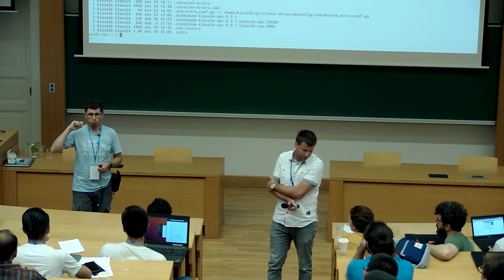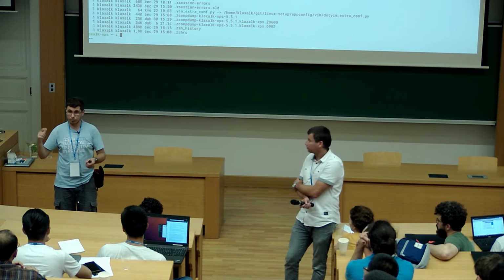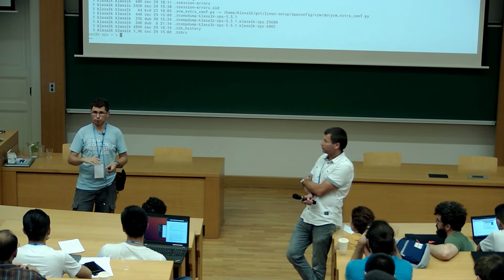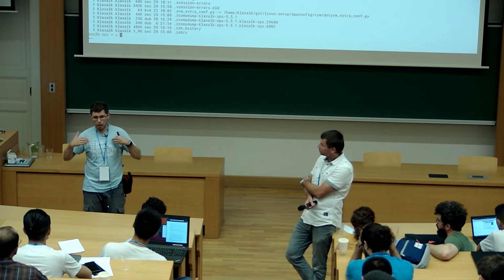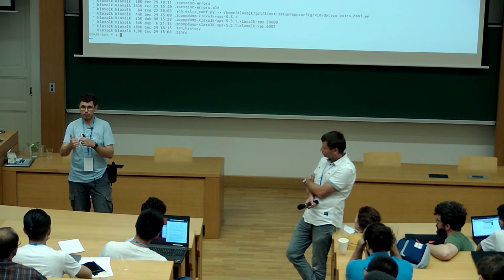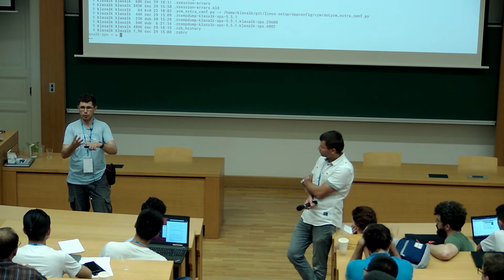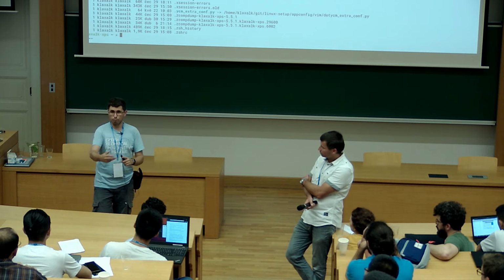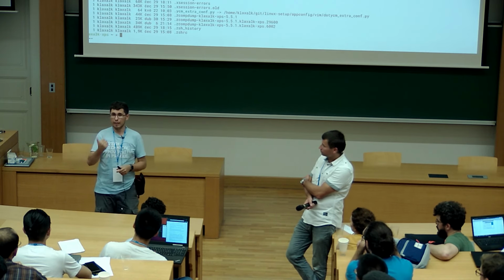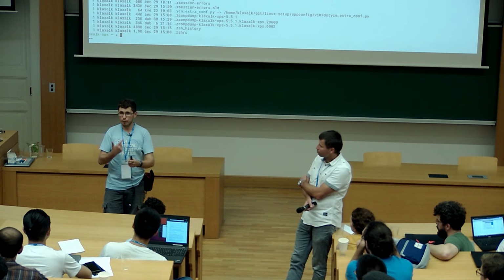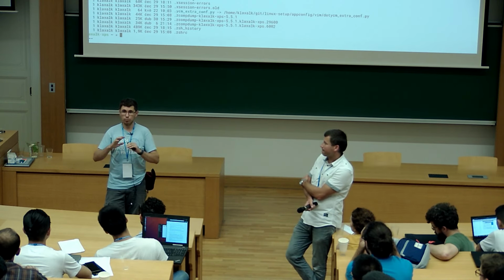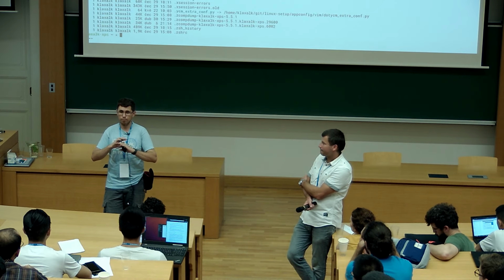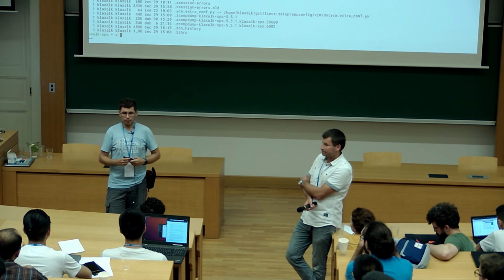We utilize only its attitude controller, which is the lowest possible level you can use. Our output to Pixhawk is 100 hertz, 4 numbers: yaw, pitch, roll rate, and total thrust. And from Pixhawk, we read out the IMU data, the magnetometer, and the GPS. That's all. We don't interface with it in any other way.